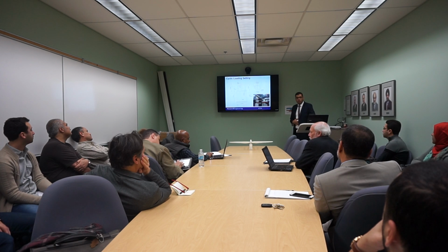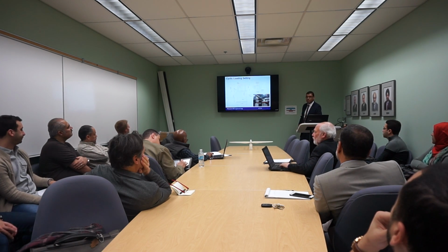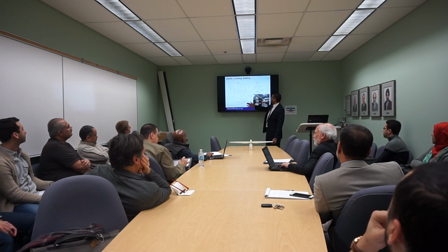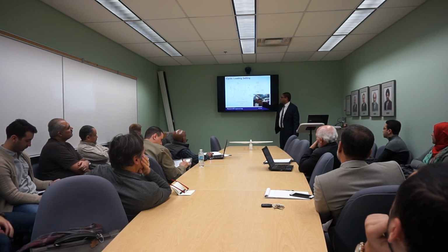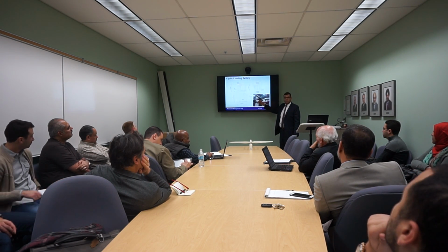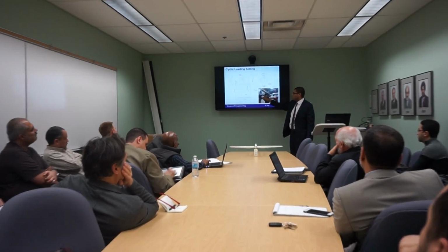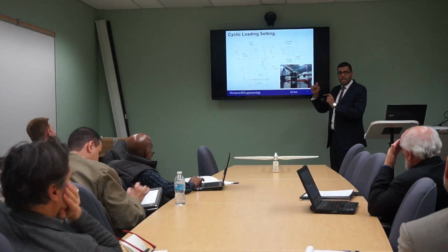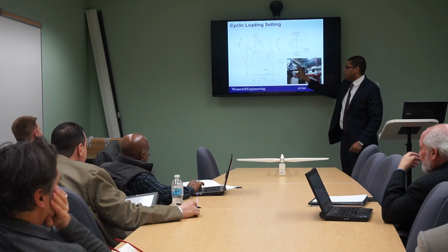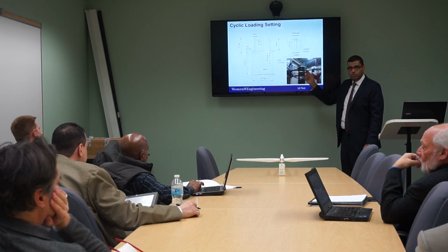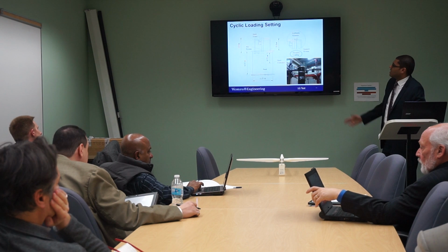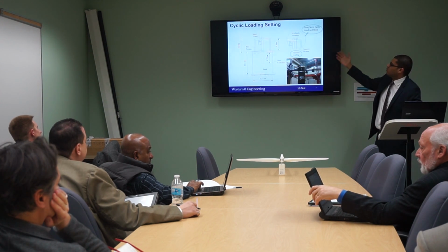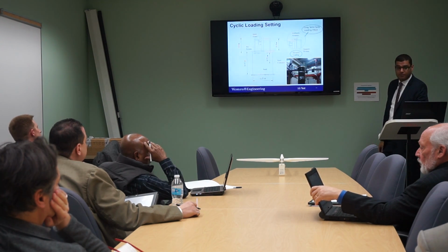After doing static load, we have done cyclic loading test. We can see also this cross section of the system. For cyclic load, we already have done this by using a hydraulic actuator from the mechatronic department. By depending on the air pressure and the size of the actuator, we'll be able to know the required load to move the pipe. So for cyclic loading, we needed to study the long-term cyclic loading effect.